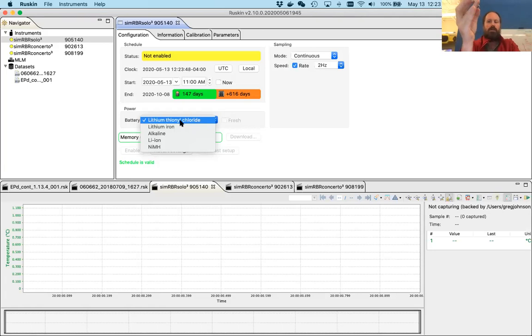So they are, in all aspects, a genuine drop-in for an alkaline battery. With lithium thionyl-chloride batteries, you must not drop them into your flashlight, your torch, other pieces of equipment, because the voltage is too high. RBR instruments are designed to deal with this high voltage, but that's not always the case.